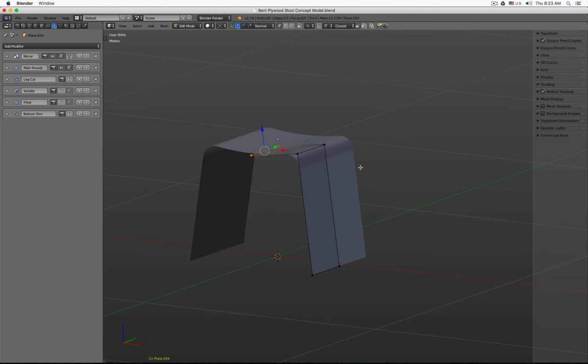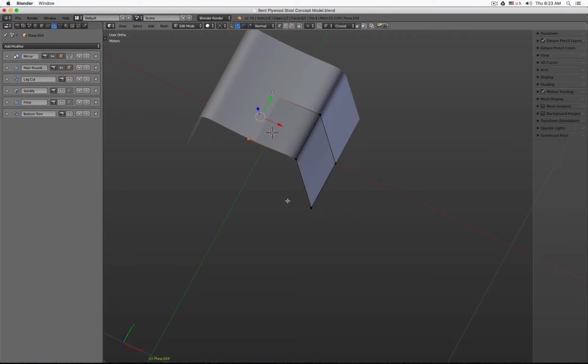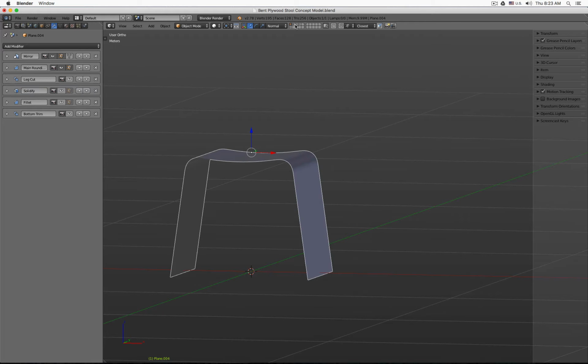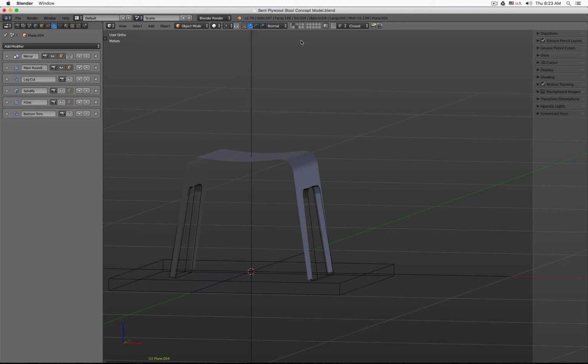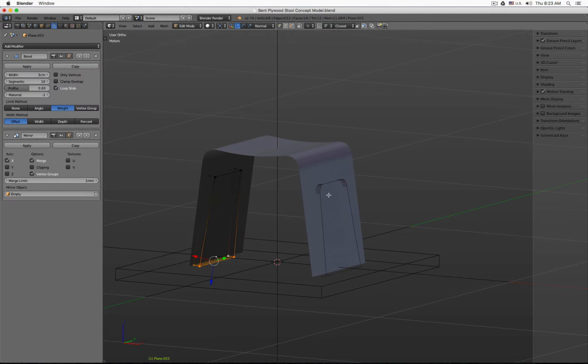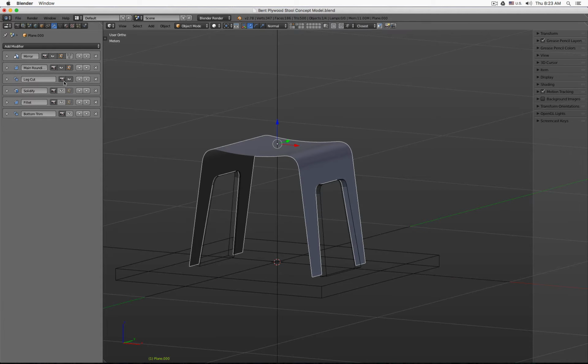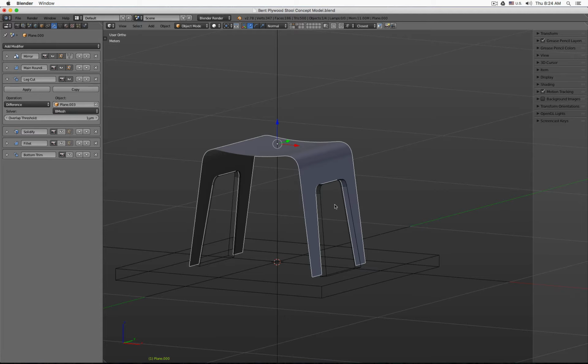So here is a very basic model. You see the shape is very simplistic, and I used the bevel modifier to round the center and the corner edges. And then via this object, where I can define the roundings, I can then, via the Boolean and difference in Bmesh, cut the space out already out of this very basic mesh.